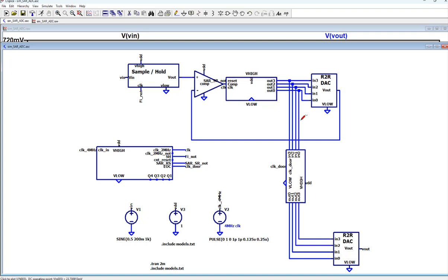All these changes at these 4 lines, including all the intermediate values from the SAR's output. Remember, if it's a 4-bit, on the quizzes you drew 5 states, starting with 1 or zeros until the final converted result. These 5 states are actually all these digital values being held on these 4 lines during different time frames. The ones that are changing don't matter because we're not sending them out before the rising edge arrives.